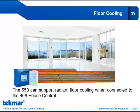Now, as a reminder, in order for the floor cooling operation to begin, you must be above your warm weather shutdown temperature. So that is a condition that has been set, that you must be warmer than warm weather shutdown to allow floor cooling to begin.